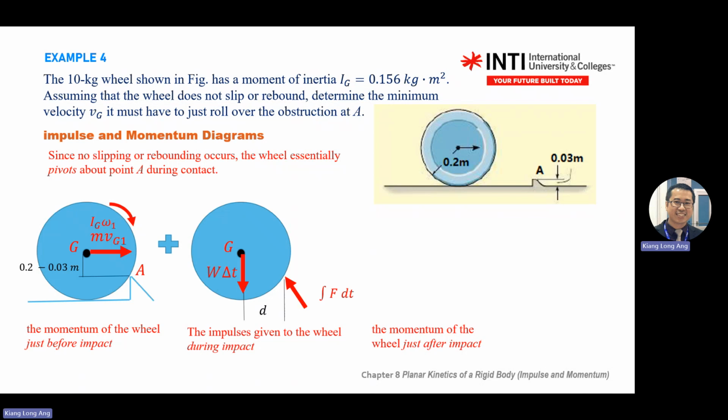Again, impulse exists as long as you have a force. It can be an external force, it can be spring force, it can be weight, anything as long as it's force. You learned about spring, you learned about weight, all these. Then there's a point A there. Why does this one point this way? Because you have a circular body drawn on the whiteboard here. For a round body, as long as there's a contact point, you always contact at one point, and it's 90 degrees to the point.